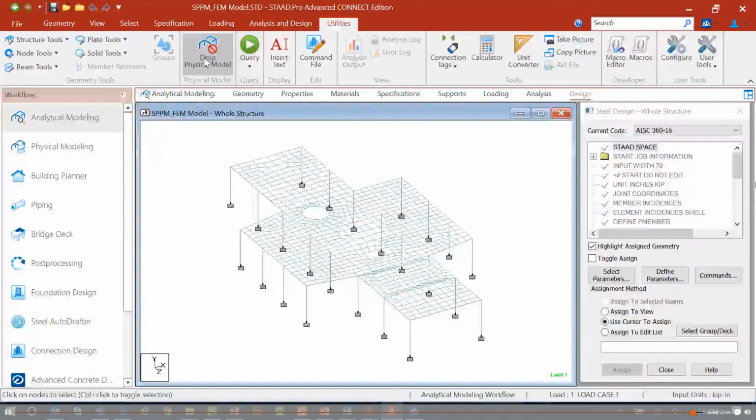I used a surface element here, like a slab, but both of those would allow you the workflow to then work with STAAD RCDC if you were designing walls. Those would have to be, of course, vertical elements, and then STAAD RCDC might have some limitations on geometry and so forth, but at least it would allow you to get your finite element mesh over to that program for the purposes of concrete wall design.